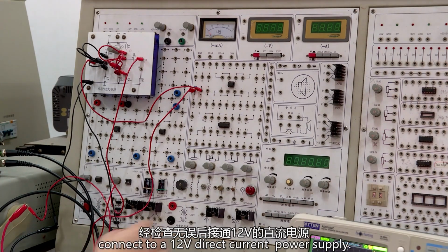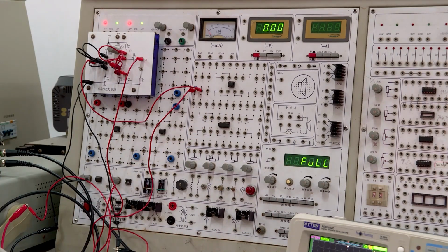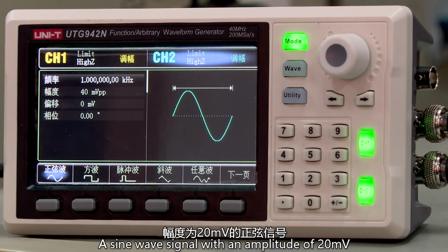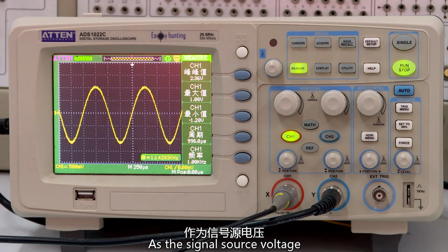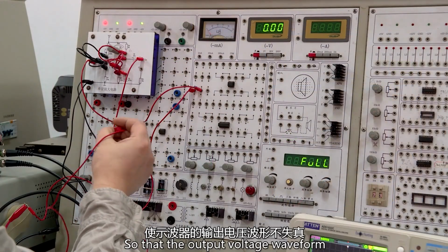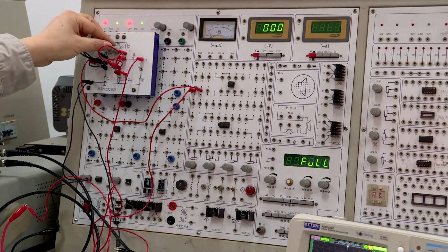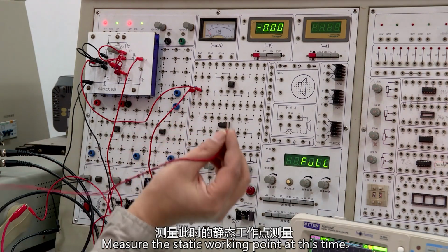After checking for no errors, connect to a 12V direct current power supply. Adjust the signal generator to a frequency of 1 kHz, and apply a sine wave signal with an amplitude of 20 mV to the input end of the circuit as the signal source voltage. Connect the oscilloscope to the output end of the amplifier circuit. Adjust the potentiometer RP so that the output waveform on the oscilloscope is not distorted. And turn off the power of the signal generator. Measure the static working point at this time.